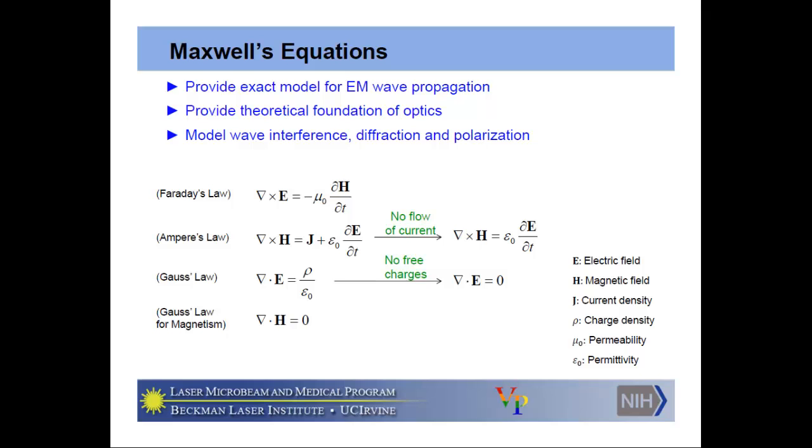That's why in FDTD, when you solve that, if you have H, you need to solve E, get that E and apply it there to find the H. You need to run step by step. You cannot go from here to there directly, because you have to solve one step at a time and move forward. That's why solving Maxwell's equations takes time. So it is limited to small spaces, even though we can apply it for large scales. But because of this solution technique, there are some practical limitations. I mean, it takes years to solve if you take a big area, like a mile by mile. It takes years to solve that kind of thing.